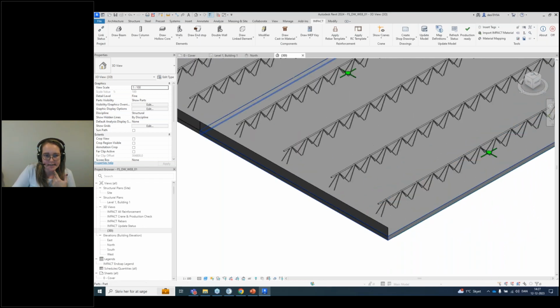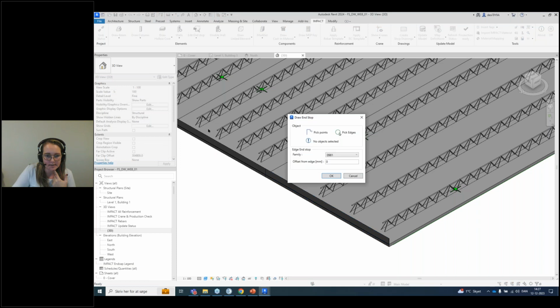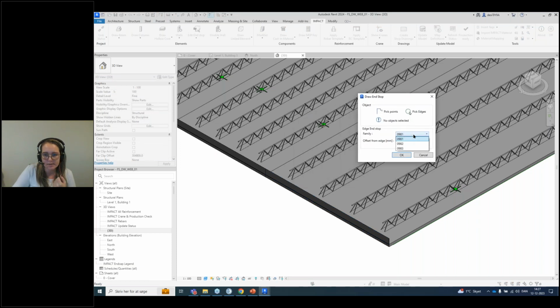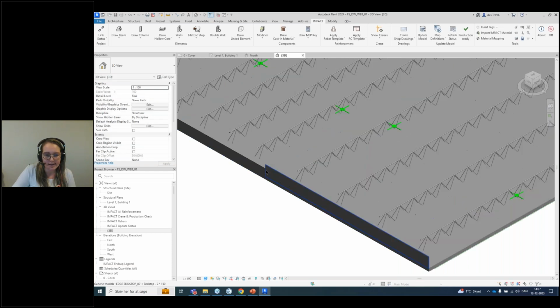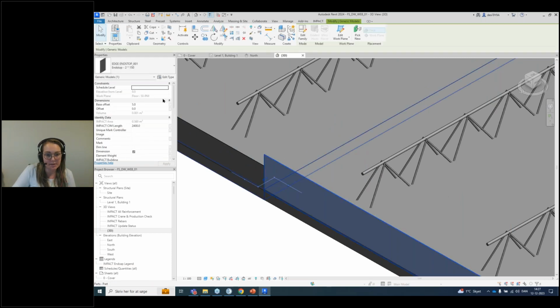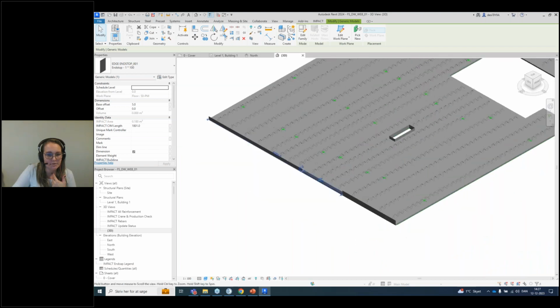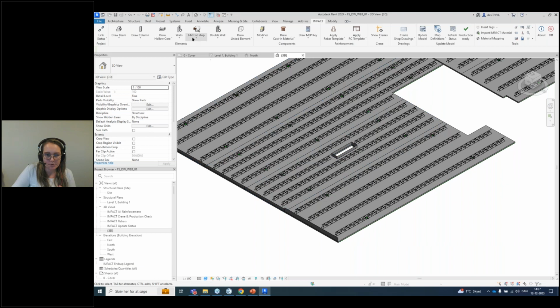Now, if you want to edit it, you can go to edit end stop, right? Select the end stop and probably select the one that is higher. This family is a little bit higher. I'm going to say OK, and then it changes to a higher 150 millimeters instead of 100. And you can do that for the rest of the elements. The same you can do with the hole.